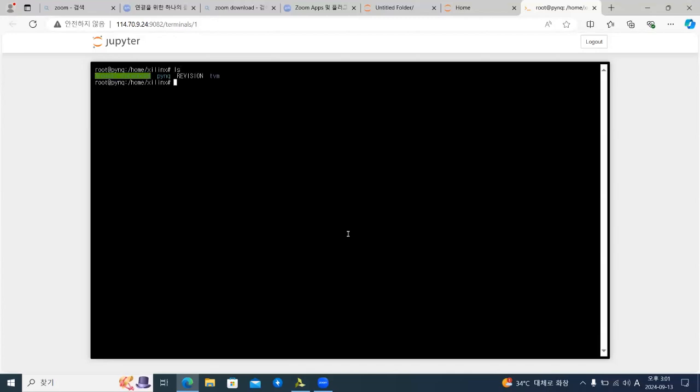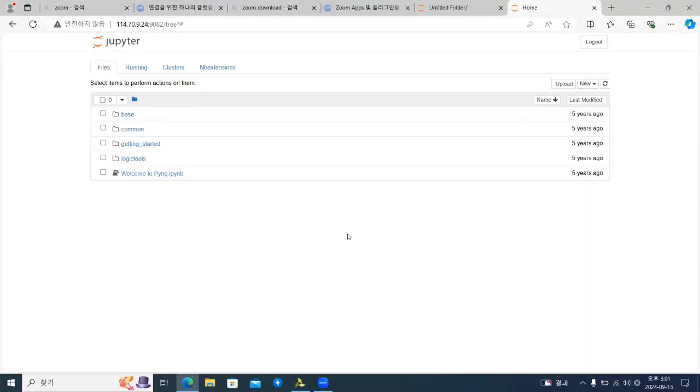And then see, this is actually running Linux on it. This is the FPGA board running Linux. If you want to use your custom hardware, you need to first program the FPGA. How do you do that? You need to upload the generated bitstream. So I will just create a new folder.